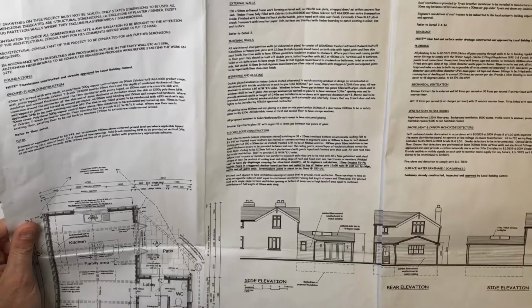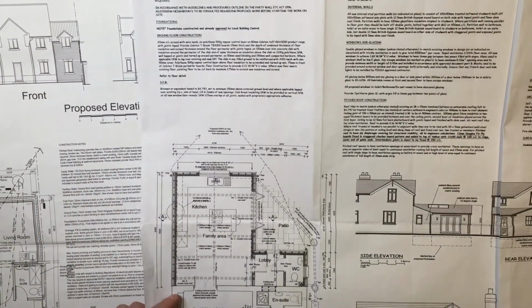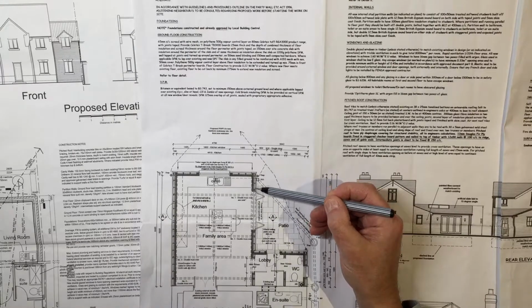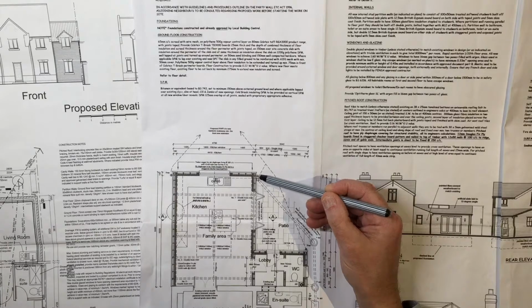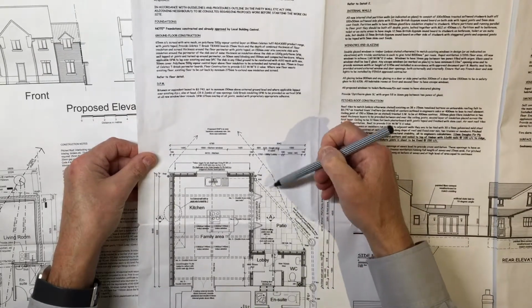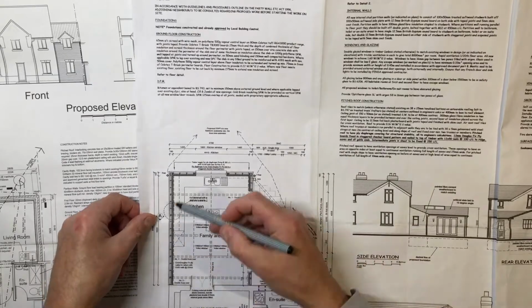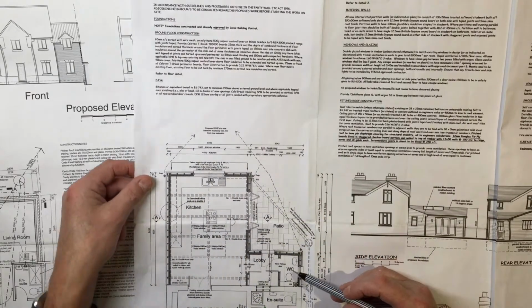Okay, this drawing I found quite interesting because it does actually show lots of hidden detail on this one as well. Can you see that? Insulation in the walls. It's a timber wall, that one, you can see. Wow. Rendered on the outside. Okay, shows the drain runs, rainwater pipe. Shows the sizes again. Quite a big extension, that one.